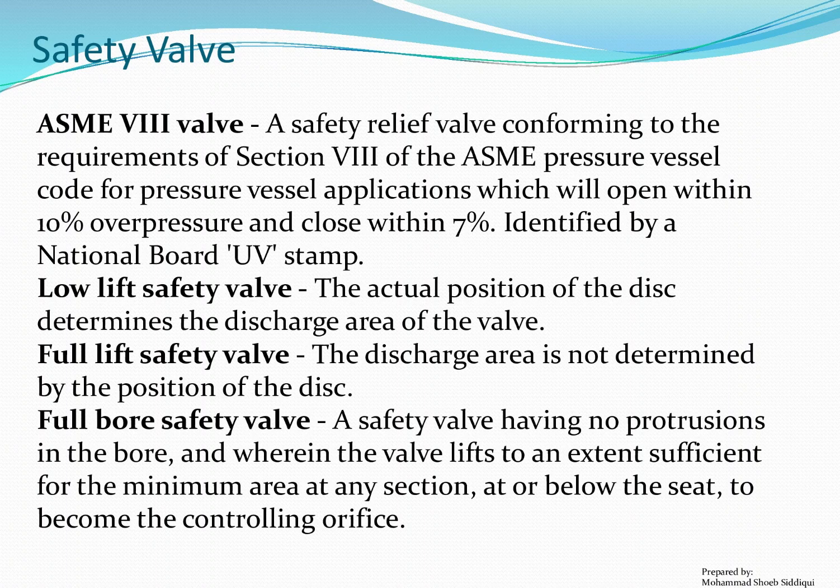Low lift safety valve: the actual position of the disc determines the discharge area of the valve. Full lift safety valve: the discharge area is not determined by the position of the disc. Full bore safety valve: a safety valve having no protrusions in the bore, and wherein the valve lifts to an extent sufficient for the minimum area at any section, at or below the seat, to become the controlling orifice.